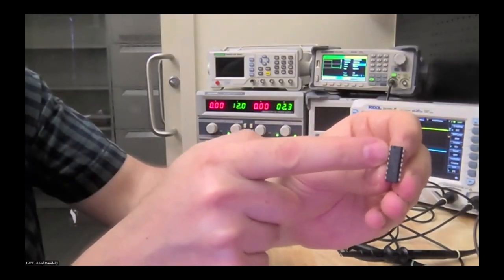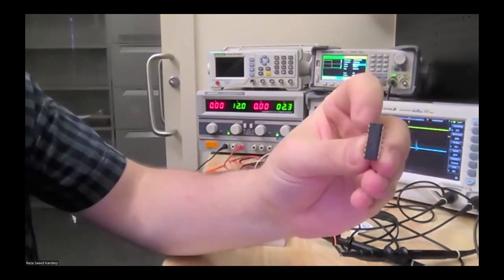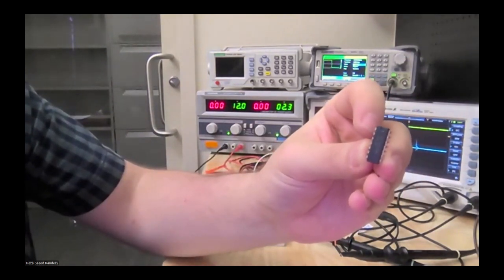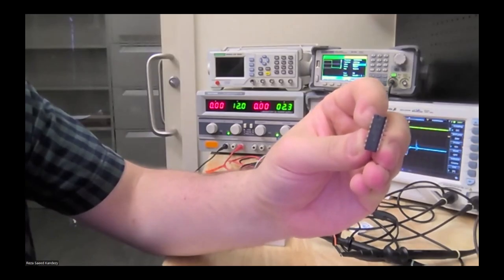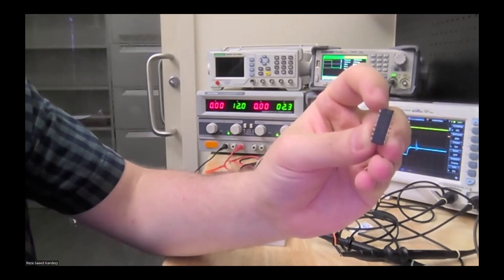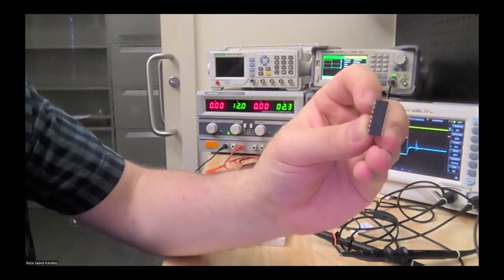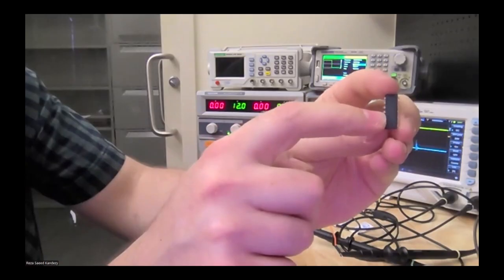Okay, so for example, in our system, we want one of the op amps, so we are going to use these 3 pins, 1, 2, and 3. The first pin is going to be the output of that op amp. The second one is the inverting input, the V minus. The third one is the non-inverting input, the V plus, where we inject the input, the square wave. And as we said, unity buffer means we have to short circuit the first and second pin. And the fourth pin is VCC.